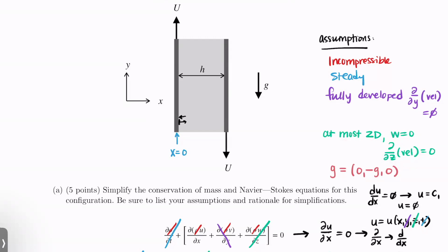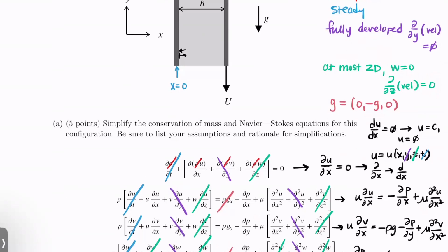Can you just write that it's impermeable, or do you want to see us show that it's a constant also? I would prefer, I mean, that kind of goes down to skipping steps. If you just wrote du dx equals 0 and then U equals 0 in parentheses, impermeable, that's fine. It's technically skipping a step, but that's fine.